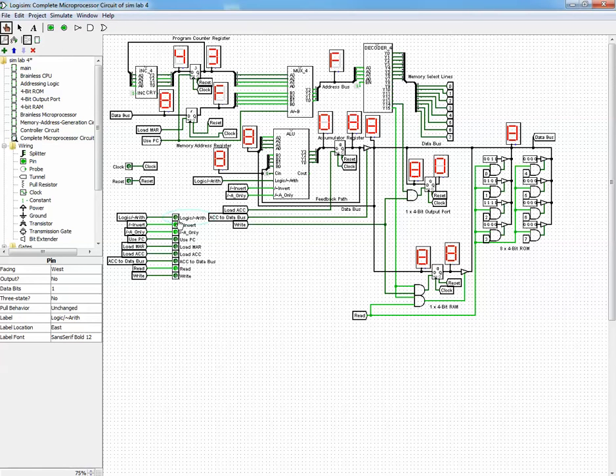So why don't we build up a circuit that controls these control inputs, so that all you need to do is to just tick the clock, and the 3 is fetched, what we call fetched, which means read from the memory, and then the 5 is read from the memory, and then the addition operation is operated on both.